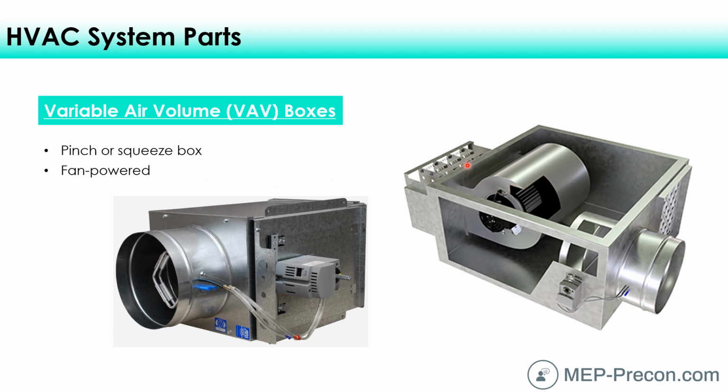And then there's a fan-powered box. The fan part comes from the ability to pull air from the plenum. So if this were installed above a lay-in acoustical tile ceiling, there is some extra heat within that plenum space given off from the lights, from the ballast of the lights. But also in office buildings, it's fairly common to have a return air plenum within the space. So it's a little bit warmer in that plenum than below the ceiling. And so this fan can pull in air from that space and use that for the first stage of heat, maybe help to blow that back down.